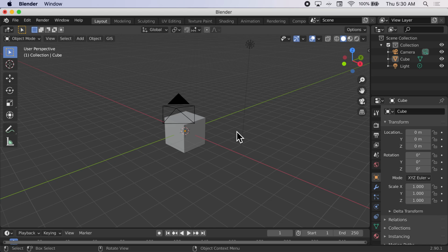It can actually change. You can reposition that. That's the 3D cursor. So notice also when I select this cube, it becomes outlined in a tangerine orange color. And when I deselect the cube by clicking off on the outside of it, it loses that tangerine orange highlight. So again, it's important to notice what you have selected. That's a visual indicator as such.